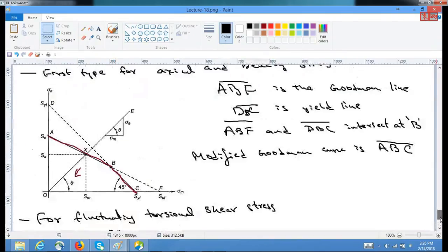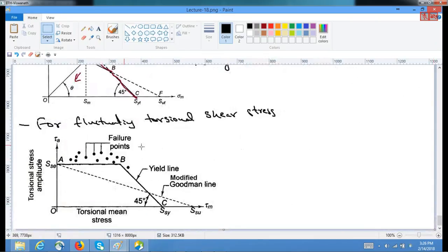For axial and bending, the mean stress does affect the endurance, so the limit keeps on reducing. However, for torsion, it doesn't. These changes are proposed as per actual experimental observations, and even though they are safe, they are less conservative compared to the modified Goodman or Soderberg line.